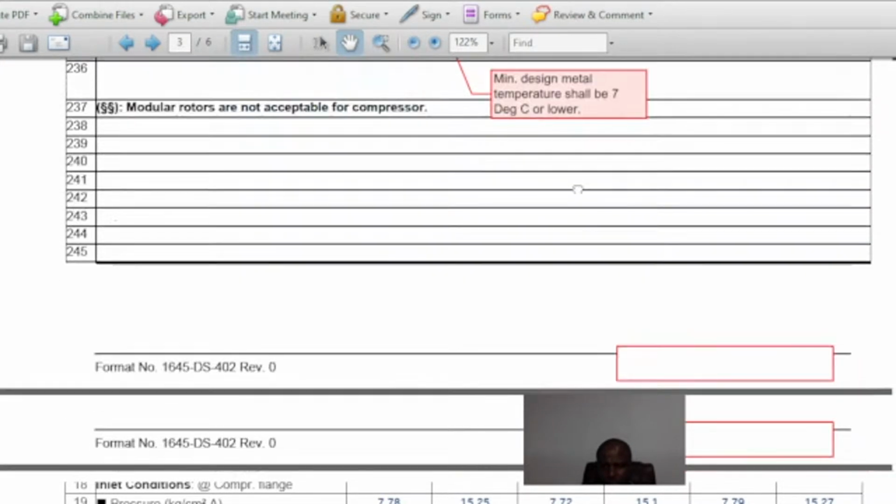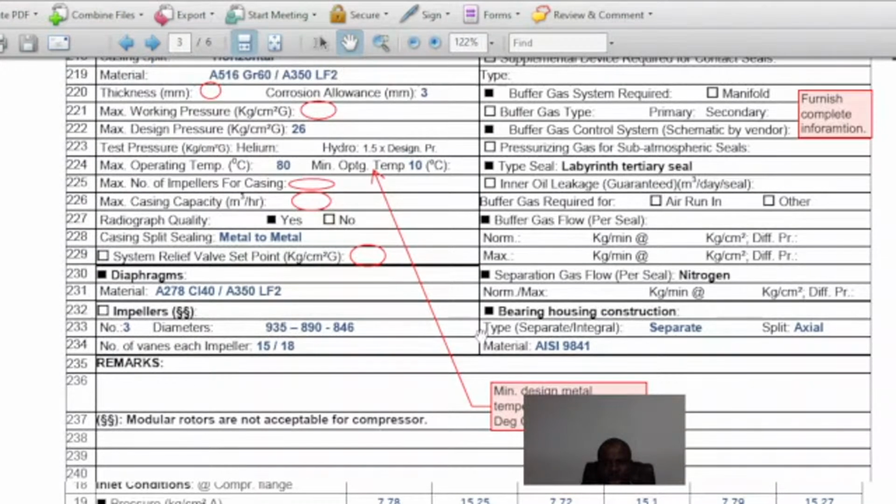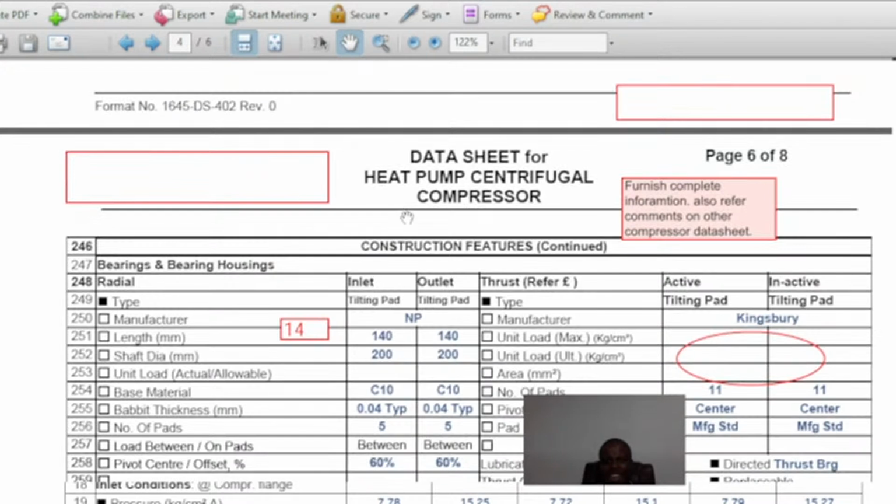Now, same way, some other data you need to be on the lookout for when you receive the equipment data sheet. Now is what are the vibration analysis, the machine protection system. The machine protection system provided. You see, machine protection systems in terms of the vibration, in terms of the temperature instrumentation, they are all regulated by what? API 670. The machine protection systems, they are regulated by API 670. You need to take note of that.